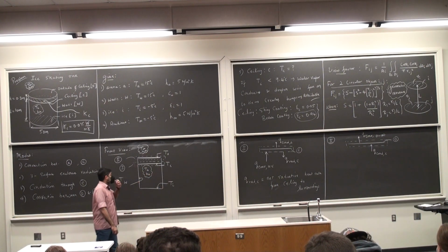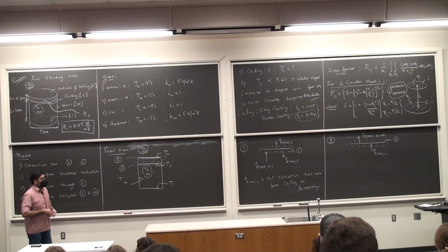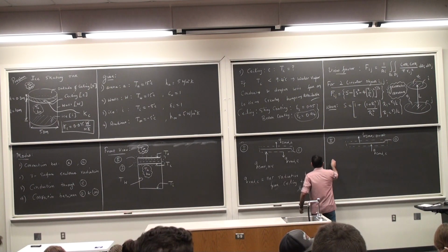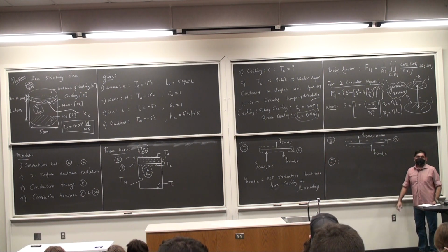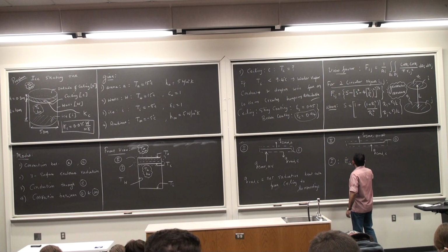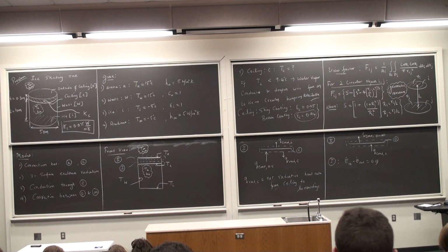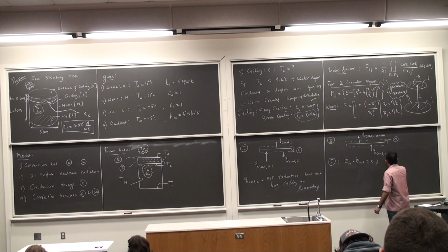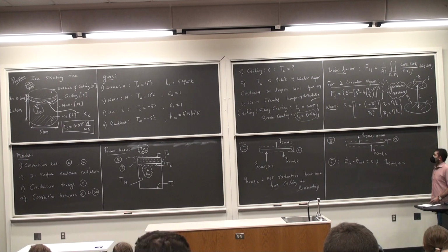No radiation because there is no information given on radiation between the outside and the surroundings. So if I just write the energy balance for 1 and 2, so from 1, E dot in minus E dot out is equal to 0. There is no stored, there is no energy generated and so on. And so if I write this out, this is just going to be Q convection between the arena and the ceiling.